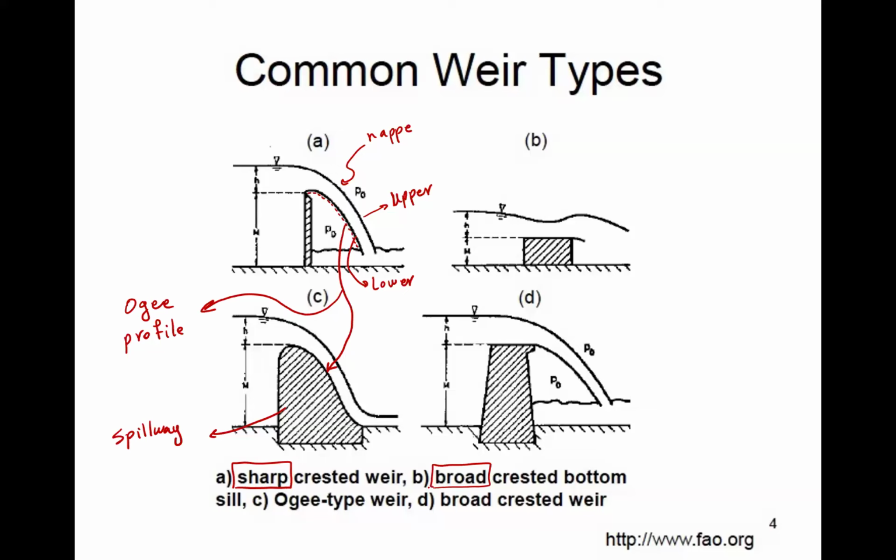Again, very practical, very common in some cases. Some dams and some structures have this kind of weir or spillway, still called spillway, but a slightly different arrangement. But here, the point is the thickness or the dimension of the crest along the streamwise orientation is not negligible. It has some thickness. But nothing changes really. It's the exact same idea. We have critical flow, we have the hydraulic control and all of that, but it's just a different geometric setup. Now, I have some examples here.